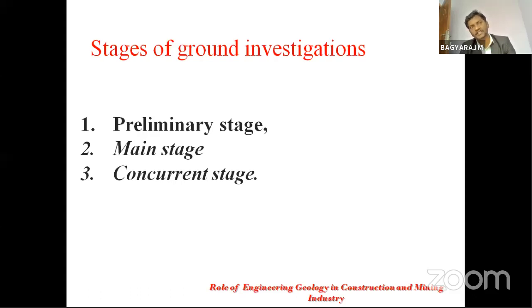Then in the main stage, we go for detailed field work, where we carry out a fresh survey at different scales to ascertain the topography and geology of the area. Sometimes for shallow surface information, we go for excavating trial pits, trenches and shafts.